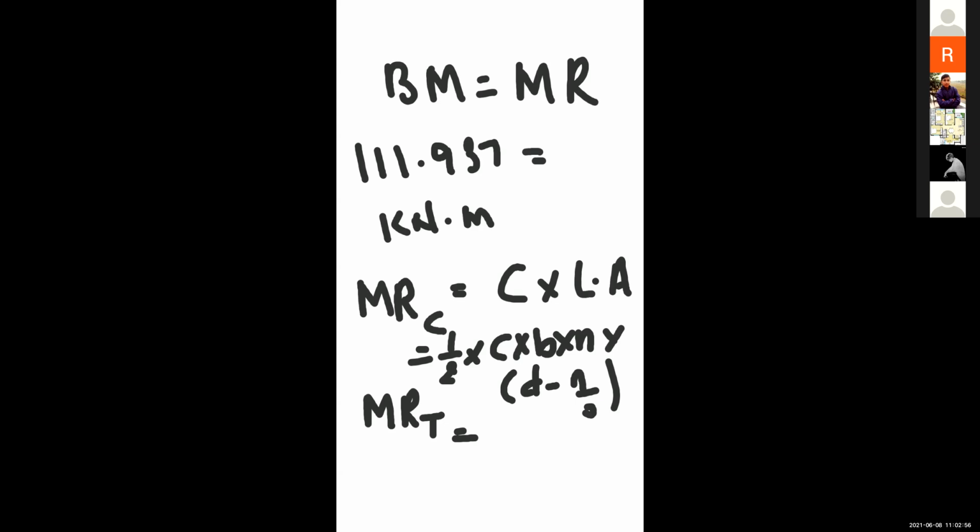Pabli Kumari, what is the formula for moment of resistance? Ma'am, tensile force into lever arm. That is T into area of steel into D minus N by 3. Repeat again.